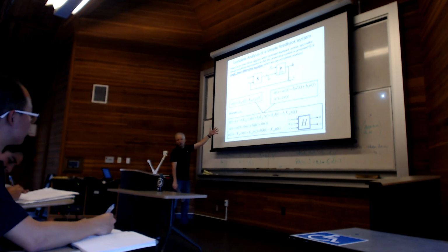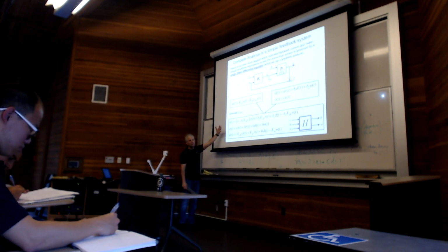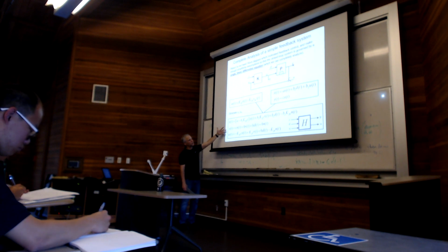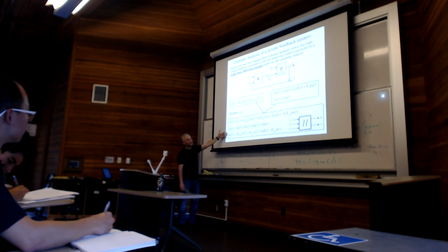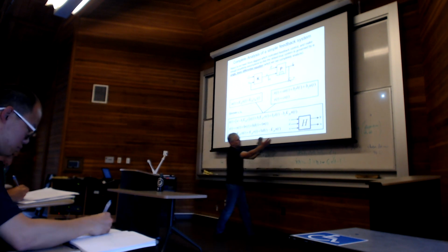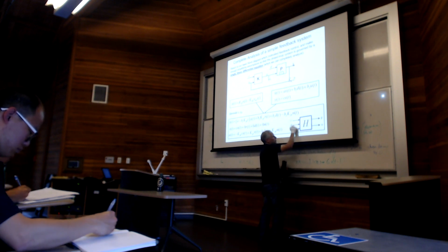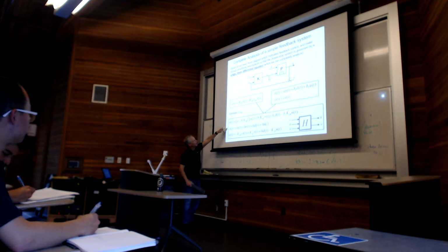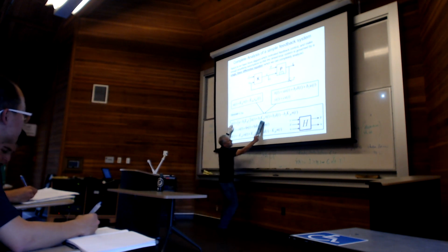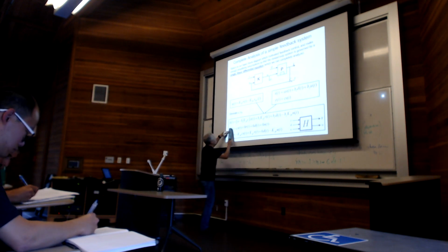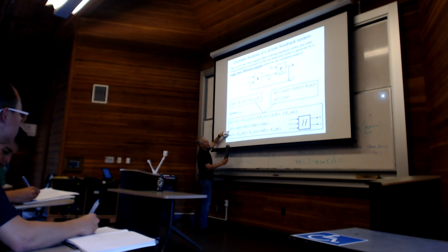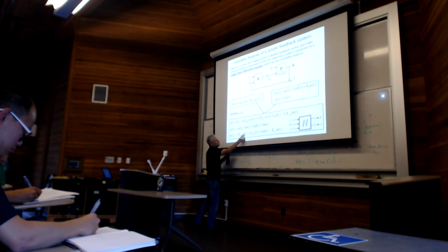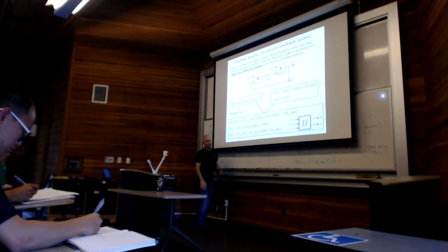So this is what I'll call the closed loop state equations. These are the differential equations and output equations governing the closed loop. From the closed loop system's point of view, I've got 3 inputs and 2 outputs, and I've got 1 state variable. There's how the state variable evolves as a function of these 3 inputs, and here are the 2 outputs that I'm interested in, which evolve as a consequence of x's evolution as well as the inputs, the forcing functions.